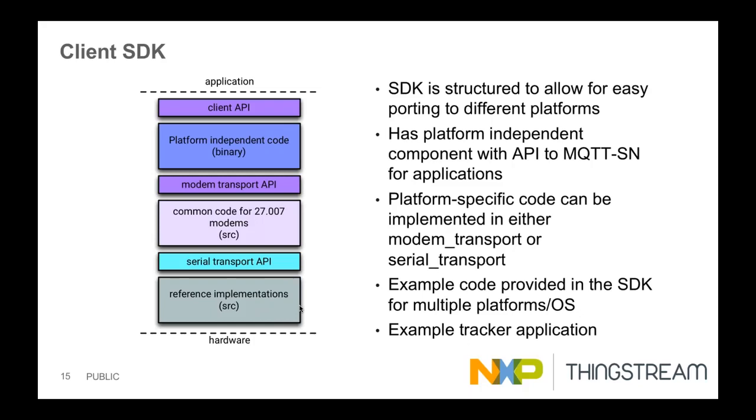that have specific functions for operating in cellular networks according to the 3GPP spec. For example, the largest manufacturers of cellular modems, and I can think of, for example, Telit, Simcom, Gemalto, U-Blox, Quectel, Sierra Wireless, all use that same common code base. They also provide modems for 2G, 3G, and LTE that are all compatible with 27.007. So if you're picking a device from one of those guys, chances are it will work with our modem transport. There won't need to be any changes there.